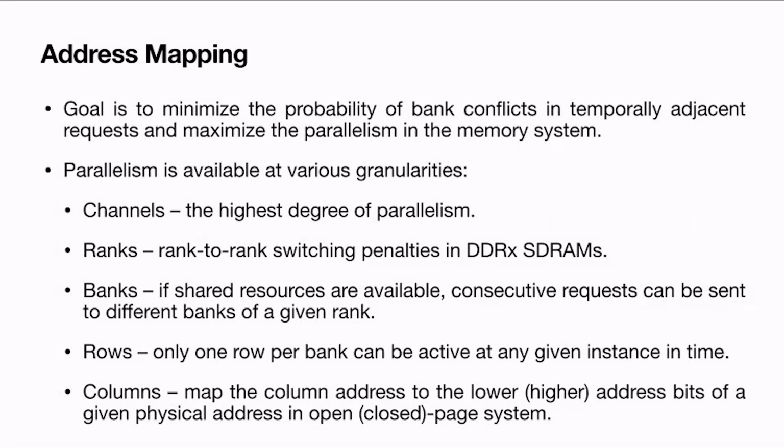And the rows within a DRAM array, only one row per bank is always active, right? If you distribute your data to multiple rows in a single DRAM bank, and you try to read those consecutively, then you will always incur row conflicts, and that degrades the performance.